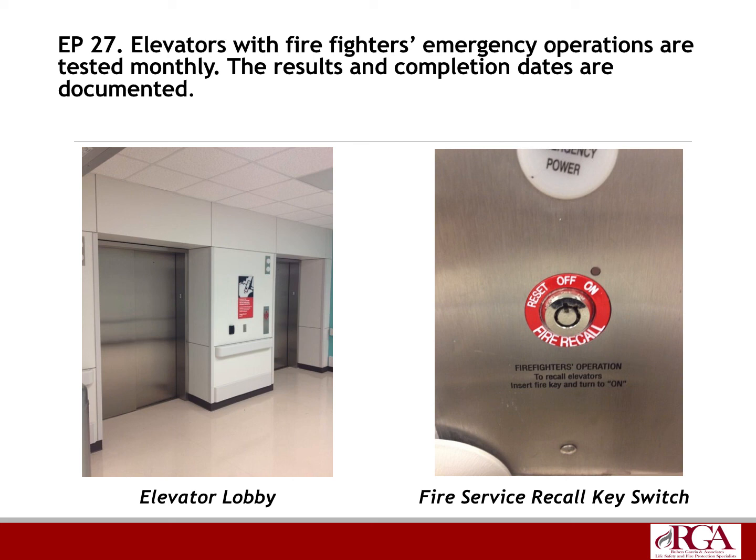So if you're just doing that bank, only those elevators are going to recall. Recall is to call those elevators down to that designated floor. The elevators are going to come down automatically. They're going to open up, and then you've got to step into each car and verify phase two. Phase two is to have independent control of each respective cab.